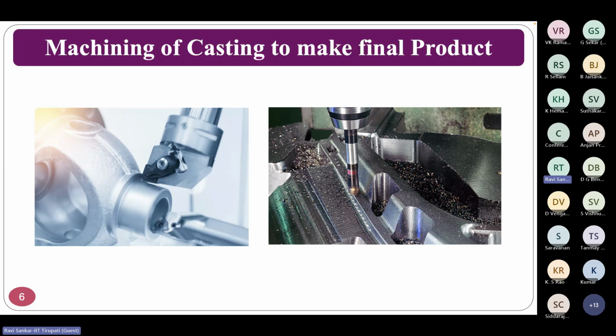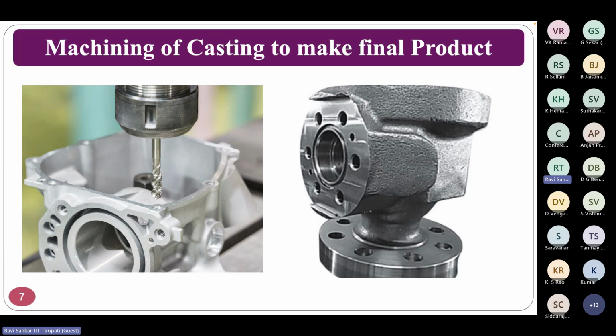So what are the common post-casting techniques that people use? Some of the processes that people normally use are the turning process, I mean to say lathe based, and milling based. These are the varieties of things people use in the arena of post-casting technologies. Now you can see some other technologies like tapping, drilling, and so on. So our main motto presently is how we can convert a casted component into a customer-satisfied product.